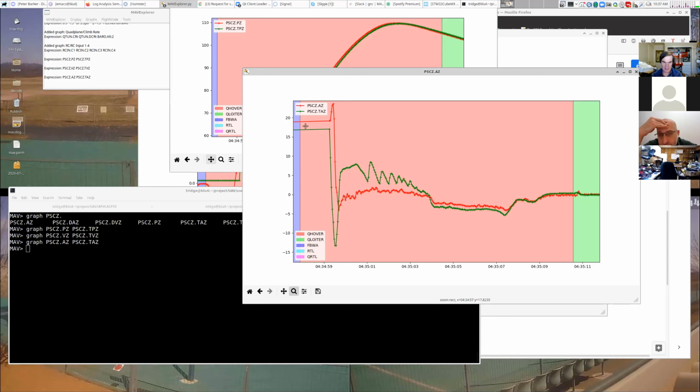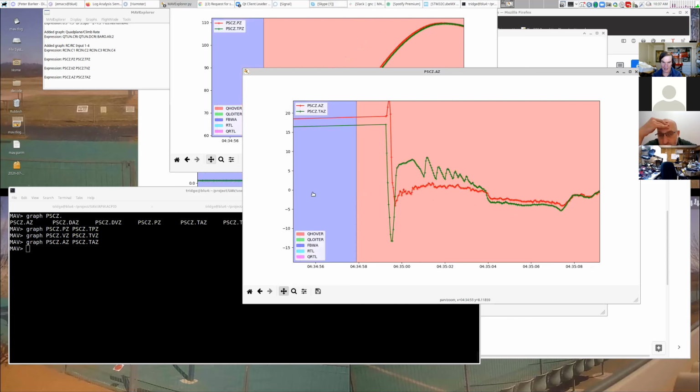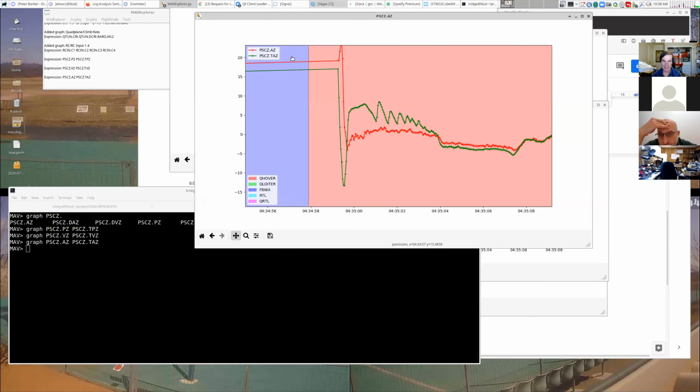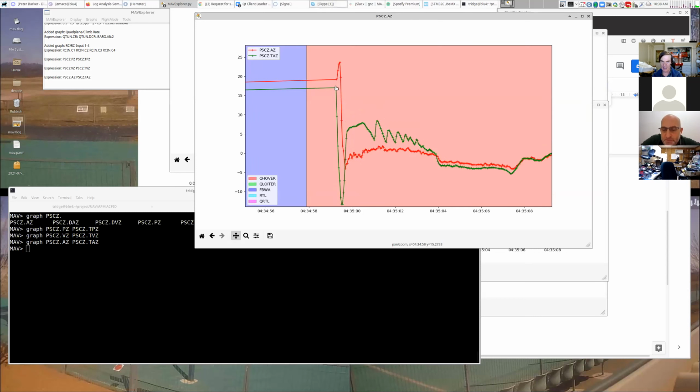The other thing is, notice there's this gap. It's in fly-by-wire here, that's this blue or mauve section. And then there's the red or pink section, where it's gone into hover mode. But you'll notice that it doesn't start giving data here. There are no data points. It doesn't start controlling the height until a couple of seconds after it flicks to hover mode, and that's because of the way the transition works. So it's coming along in fixed wing, and the first thing it does when it transitions is start bringing the nose up under fixed wing control. That's because this controller was inherited from controllers where, in high speed flight, it's your control surfaces, your elevons, that are dominating.